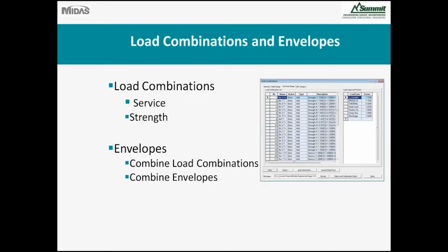For a quick check of what the ultimate strength or maximum service stress was, I also then combined my envelopes into envelopes. I certainly divided that back out to get an understanding of what the controlling load combination turned out to be, but to get a quick check of what your ultimate moment is or what your maximum service stresses are, it's handy to be able to combine all the envelopes together and just click on one button once the model is run and your performance checks.